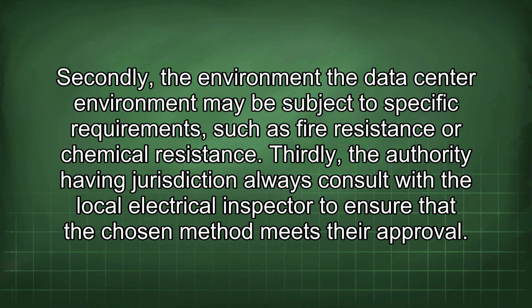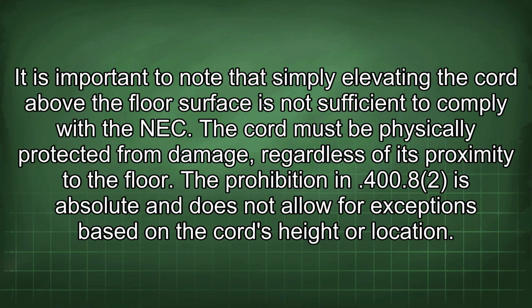Thirdly, the authority having jurisdiction. Always consult with a local electrical inspector to ensure that the chosen method meets their approval. It is important to note that simply elevating the cord above the floor surface is not sufficient to comply with the NEC. The cord must be physically protected from damage regardless of its proximity to the floor. The prohibition in 400.8 is absolute and does not allow for exceptions based on the cord's height or location.